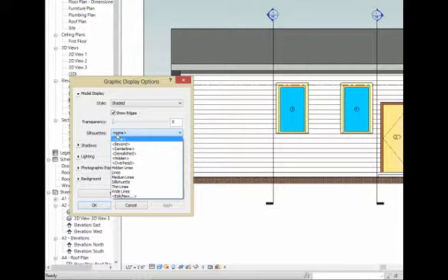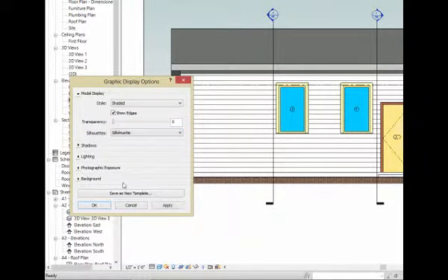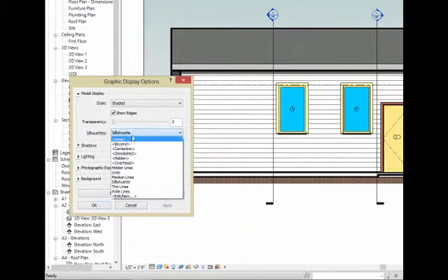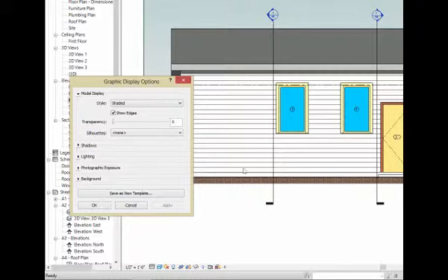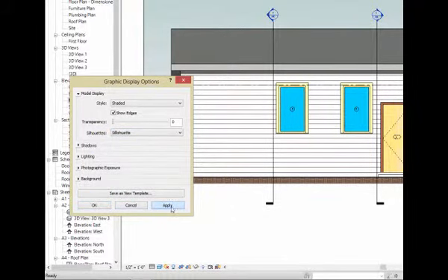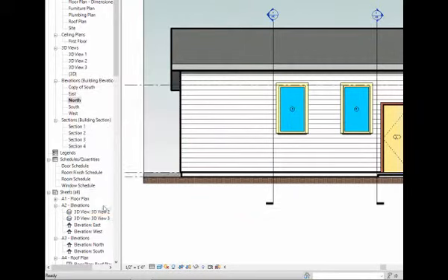I could go ahead and put in a silhouette line. So I'm going to put a really heavy line in there that I defined, called silhouette. So let me show you. With none, you can't really see much of a distinction between the edge of the building and what's behind it. Silhouette just puts a heavier line in there. Okay, so people who do a lot of architectural drafting tend to like that. It looks just a little more pleasing to the eye.